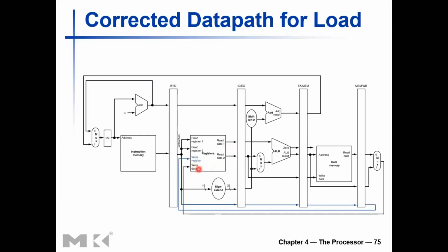So that is one of the first things happening in that stage, which we didn't discuss earlier. Actually it happens in the write back stage or at the end of the write back stage, but it will coincide with the instruction decode of a subsequent instruction, right? The writing will happen, but at the same time, some asynchronous reading will happen for a later instruction. So will that create any issue? Writing of the register takes a small time.